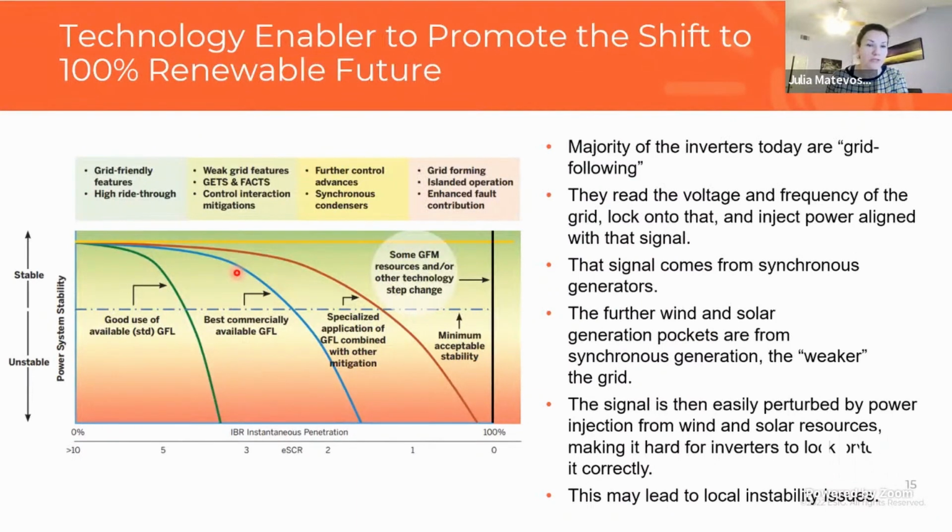These controls are specifically designed to avoid the control interactions that I mentioned. Grid-enhancing technologies such as dynamic line rating and flexible power electronic supporting devices are also more broadly used now to support the grid, because you have fewer synchronous generators and more inverter-based resources, and something needs to support the reliability of the system.